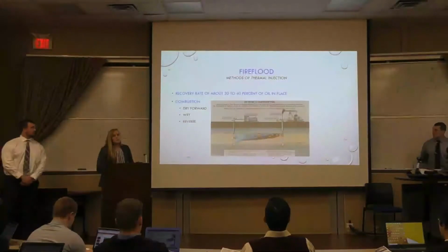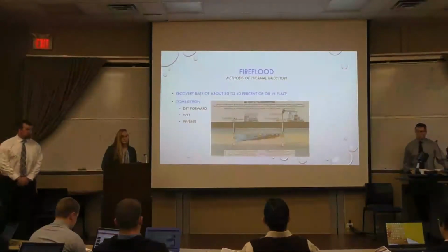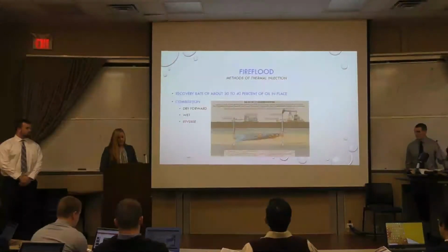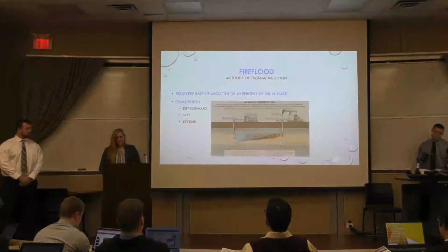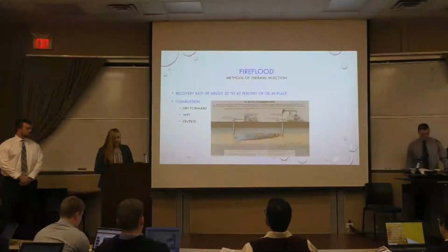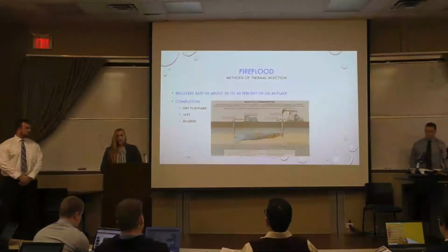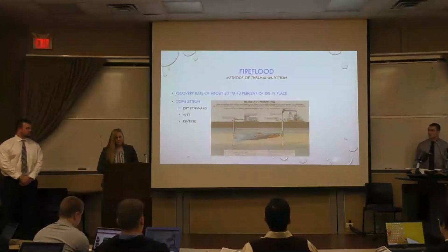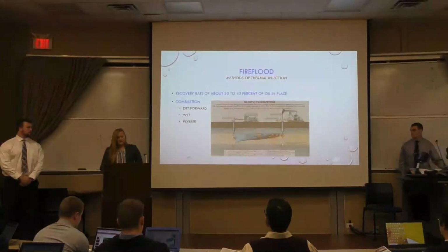The last method is fire flood. In this method, heat is generated inside the reservoir. Fire burners are used to provide fire burns into the formation in shallow situations. In deep formations, the fire is generated by injecting air and other mixtures through the injection well. The hot gases provided by the fire flames reduce viscosity in oil, which forces the heated oil towards the producing well. In some cases, water can also be injected, which turns to steam, creating an additional force to help move the oil.